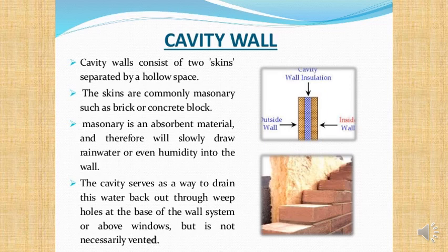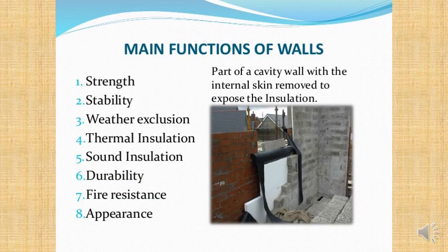Just like many of you might live in a house with double glazing on the windows, and the house stays cooler in the summer and warm in the winter. It's because of insulation. A cavity wall is one way of doing that. So a cavity wall basically is filled often with a synthetic material. So here I think it's being filled with polystyrene. And yeah, the main advantage is insulation. It's thermal insulation, but also sound insulation.